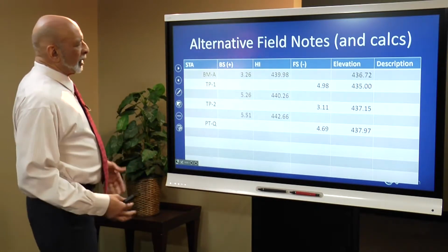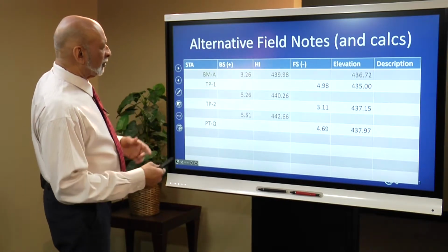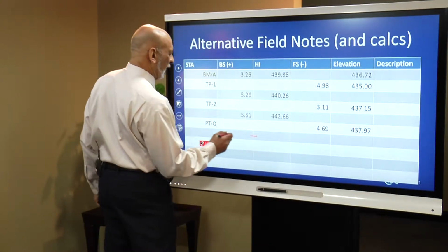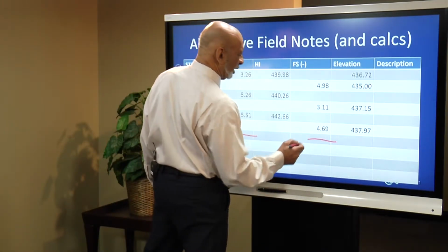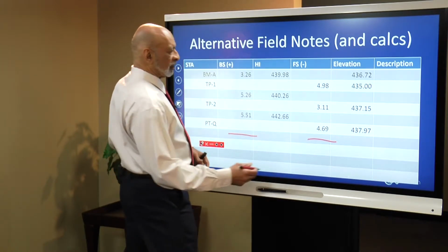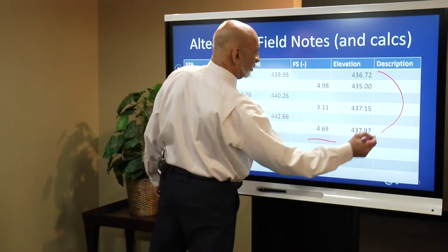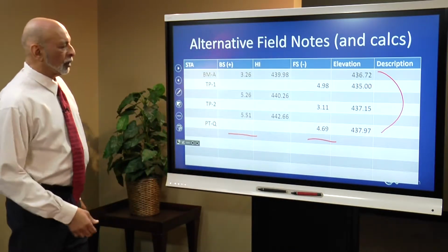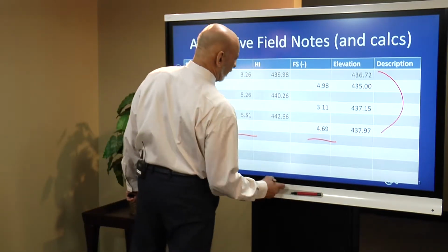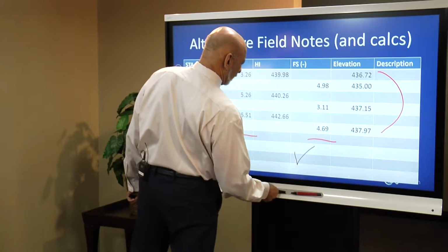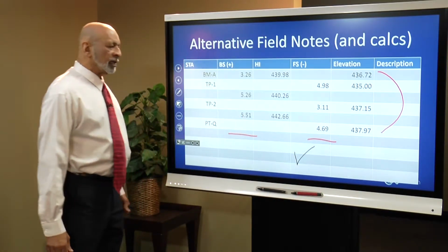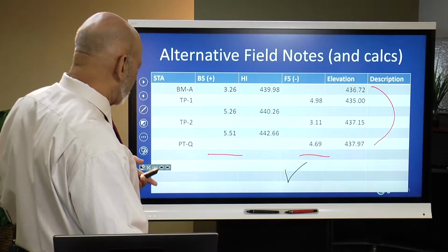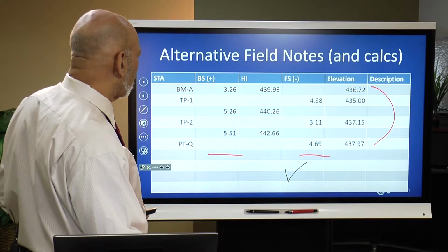In other respects, the math, the numbers, everything else is the same. You can still do your math check. You'll still have this situation where you can add up your backsights and foresights, get the difference, calculate the difference between your starting and your ending elevations, and still do your math check, and to be able to signify that, yes, I have done the math check, my math checks out fine, and here is my survey data for whatever the next step in the processing happens to be.